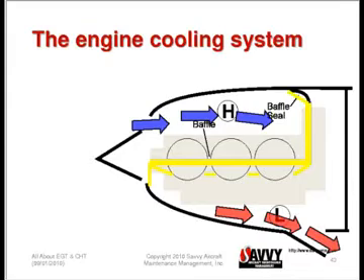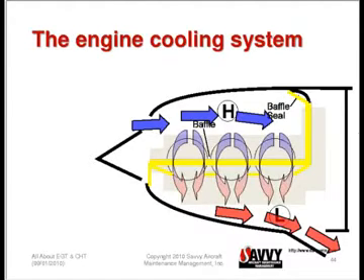So the efficiency of our cooling system is pivotally connected with the proper positioning and fit of all of these baffles, so that all of the air that passes from the high pressure area on top to the low pressure area on the bottom has to actually go through the cylinder cooling fins and cool the cylinders, and that's the path of the air that the baffles are intended to create. So anything that's wrong with the baffles or the baffle seals, the baffle seals are the flexible stuff, and the baffles are the rigid metal stuff.